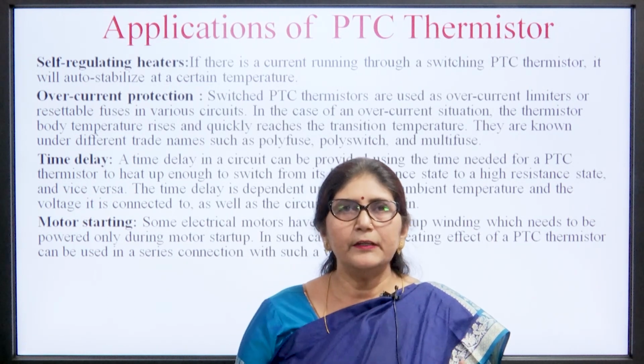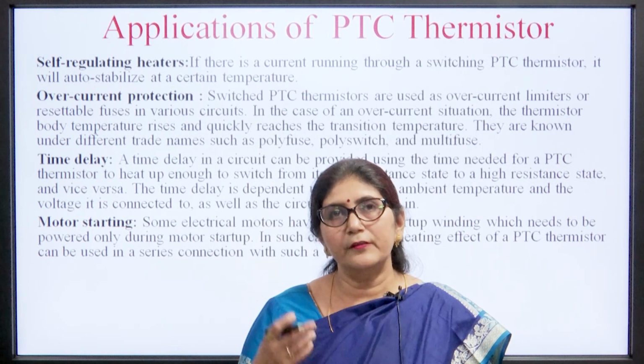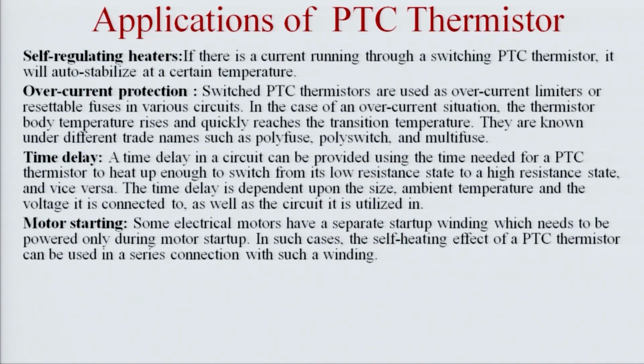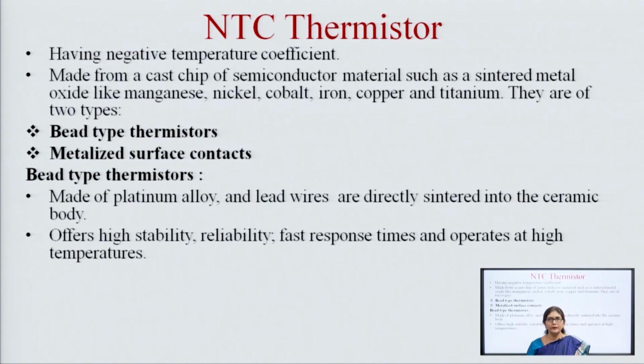So, these are the applications. We can use PTC for self regulating heating, for overcurrent protection, to provide delay time, and to provide starting of the motor. It can start the motor when a different starting coil or starting windings are used. So, these are the applications of positive temperature coefficient thermistors.